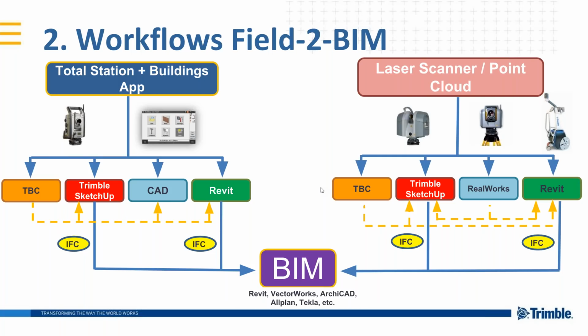Exactly. So as I said, in BIM we have different elements in the whole model, and everything is specified. So for the facade, in our case, it's a kind of structure. We start with the site, then below the site is the building, below the building is the floor, below the floor the wall, and inside the wall the windows, the doors. So there is also a relationship between the elements. I cannot place a window if I don't have a wall. So you can also create facades and everything, but it has to fit inside a BIM object: a wall, a window, a door, a roof, a staircase, etc.